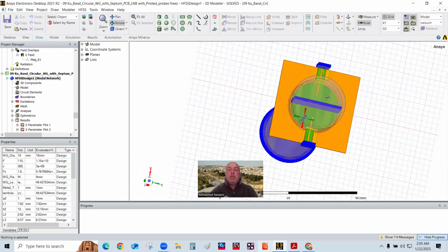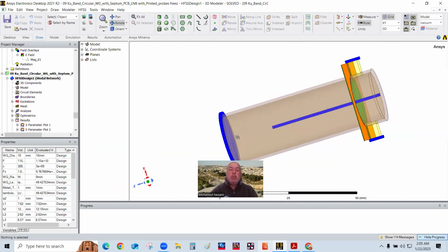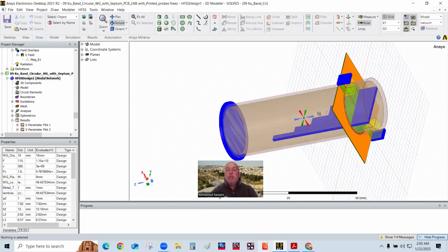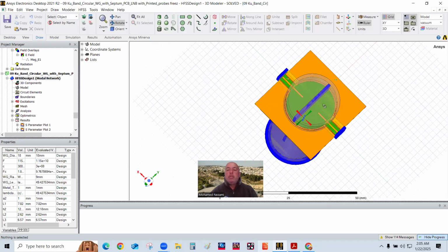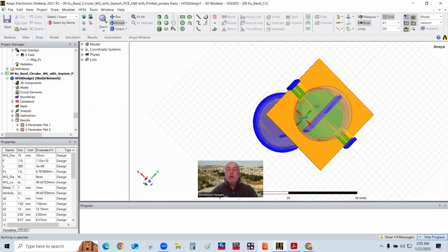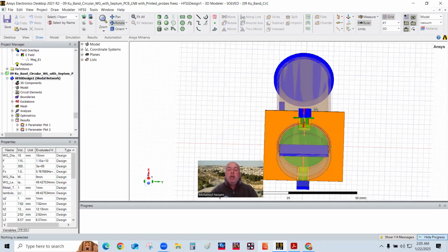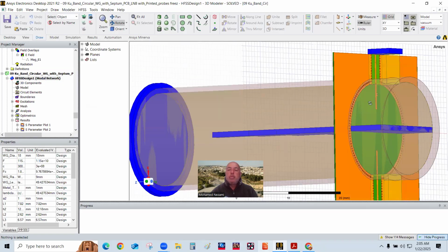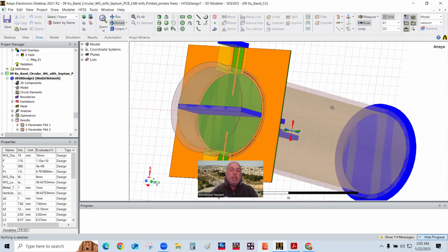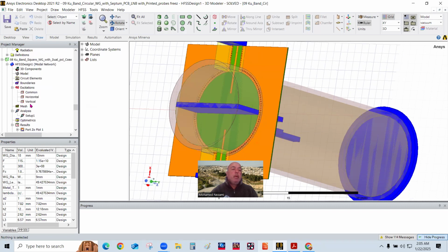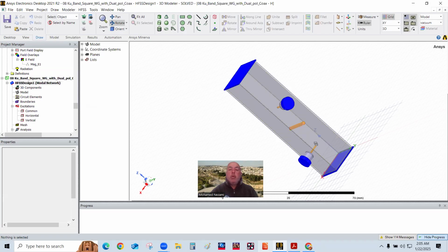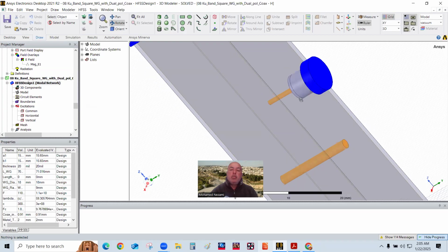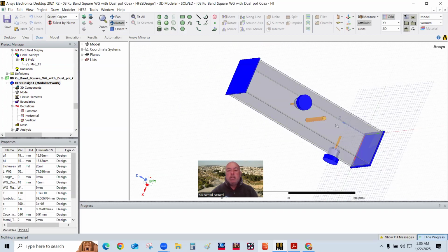The whole assembly of going from basically the signal that propagates down from the horn, this end would be connected to the horn, through the septum, and then through 2 halves of the circular waveguide, which becomes a rectangular waveguide, to go into this PC board in here, where we would pick the signal through probes, be it printed probes like this one, or be it wire probes like it is in this one here, where we can go through a transition to the board on top, which I haven't done in this case.